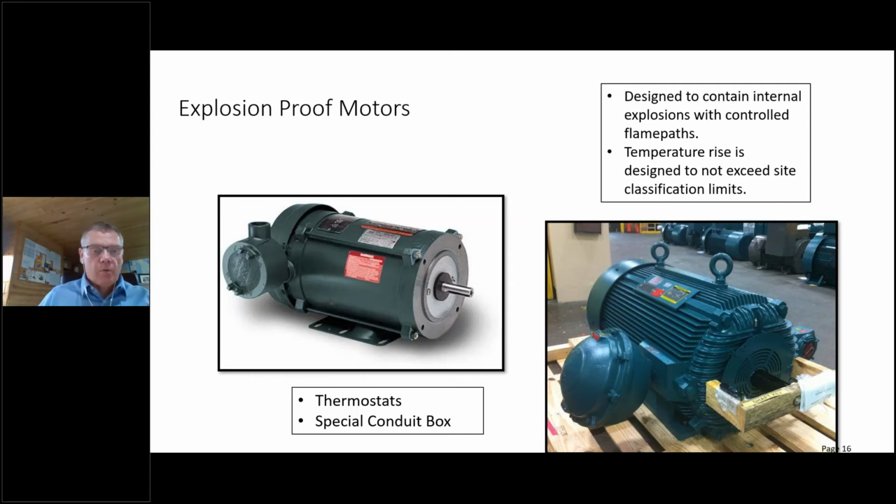I'll just move on fairly quickly on these ones. I just want to show some other examples. There may be some questions after about explosion-proof motors, but in the rest of the world, other than North America, they don't actually call motors explosion-proof motors. They actually call them flame-proof motors, which is a more accurate description.